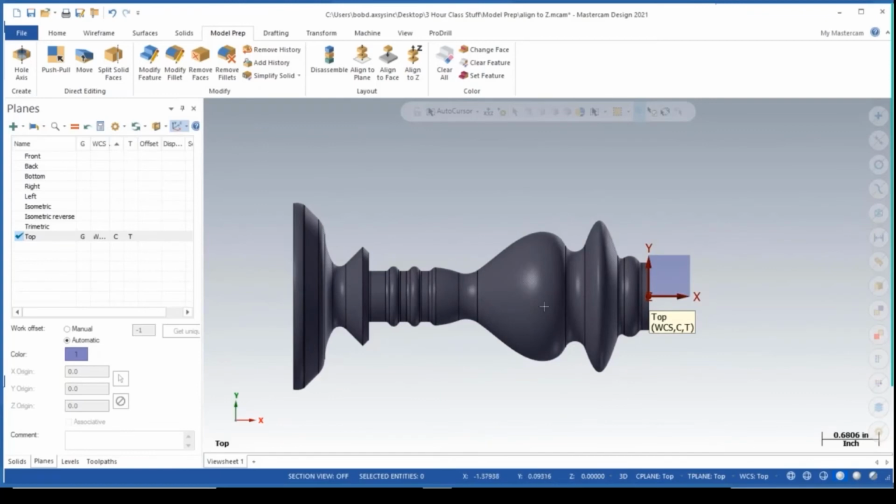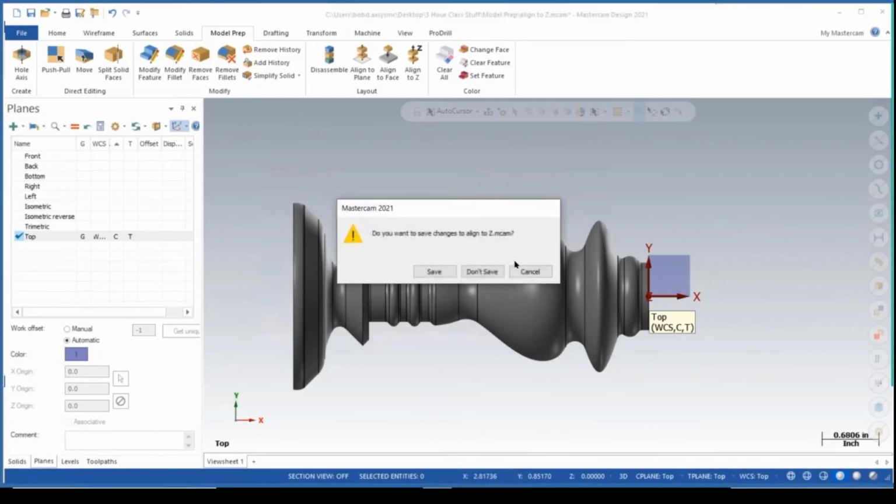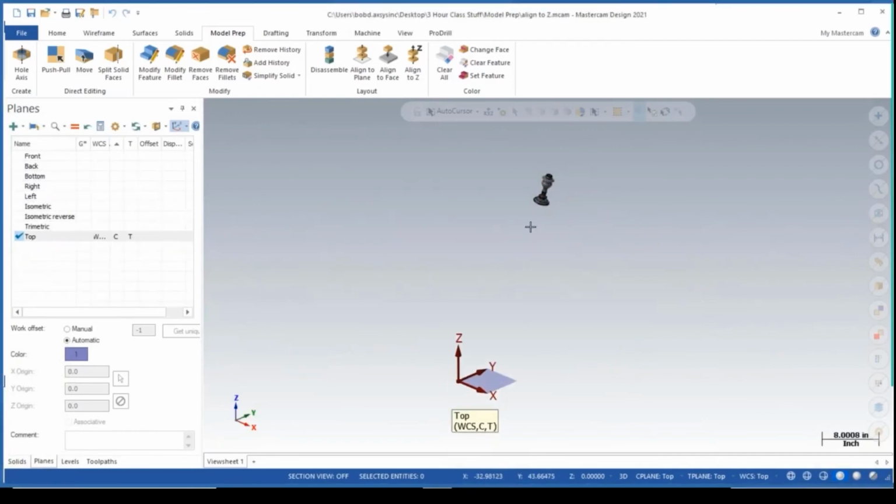The difference is if I have any engineering change to this that comes back either from the customer or from my CAD department, that engineering change is going to live when I open it out here in space. So if I move this geometry to here and I need to use this new geometry, I'm going to have to move the new geometry, recalculate all my toolpaths. If I created the custom WCS where this lives, I wouldn't have to do anything other than import the new geometry, create or select the new geometry that I had to machine if that needed to happen, and I wouldn't have to manipulate where this lives.